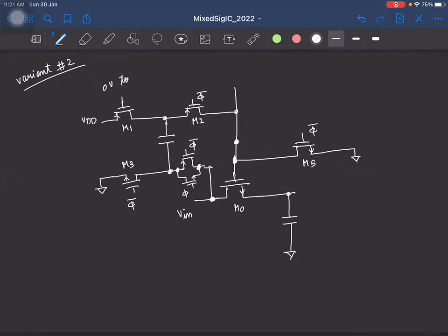Okay. So ideally, if you're not connecting this to the gate voltage, we would want to ensure that this switch is always off irrespective of the input voltage. So we would want to connect the gate to VDD to turn the switch off, right? So this would require that we need to generate a clock going all the way from 0 to 2 VDD, right? And this will require higher voltage supply as well, right? So instead, people started to see what happens when we use an NMOS switch. So let's say I use an NMOS switch.